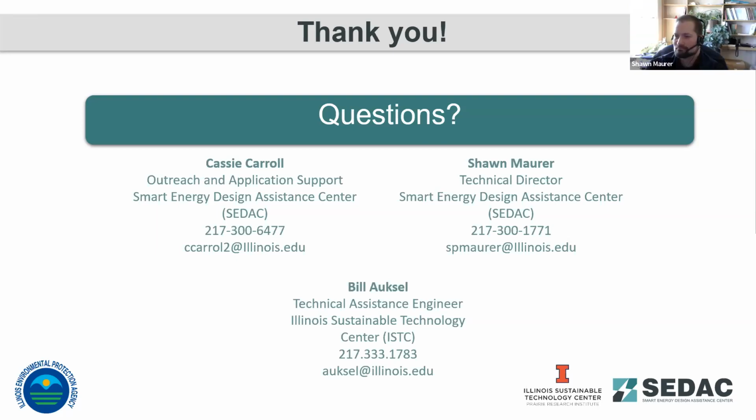Bill has a question here. Would a good rule of thumb be over 10 horsepower with variable operations, but running over 2,000 hours a year? So maybe the concern here is with such a small pump with low power consumption, you may not have the payback in cost of adding that VFD and then seeing that energy savings because it is such a small pump.